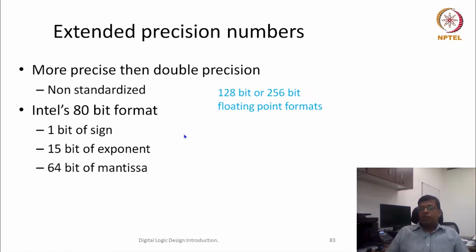Okay, so the idea here is that it gives us freedom to choose how many bits, and because your hardware is going to be custom, nobody else is going to use your hardware firmware, so these people can decide their own floating point notations. But if your hardware and software need to talk to each other, let's say we are writing a piece of software which we need to use on an Intel machine as well as an AMD machine or some other machines, then the format has to be interchangeable, or basically all of them should understand the same format.